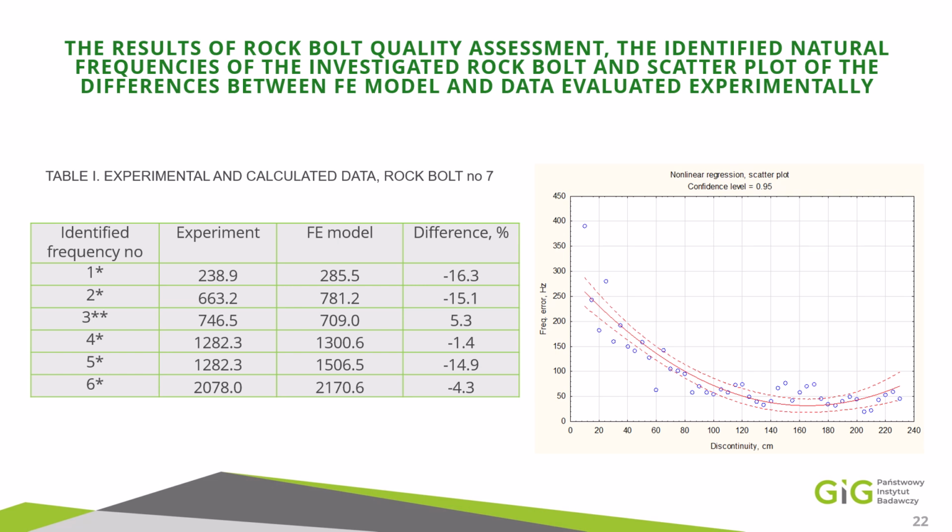The specific preparation of grout cartridges matters. Too slow insertion may result in not fully mixing the grout, especially at the end of the rock bolt, I mean this lower part, and also may cause lack of grouting.